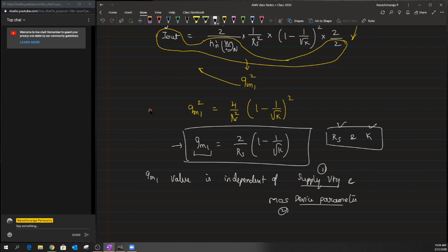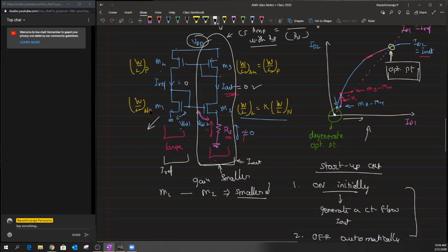Okay. So now having stabilized this value of gm1, having a constant gm1 not only stabilizes the value of gm1 throughout the circuit, but also all other transconductances, say for example gm4, gm3 and gm2. All the transistors' transconductances are also being stabilized, just because the current flowing through these structures is all derived from the same self biased network.